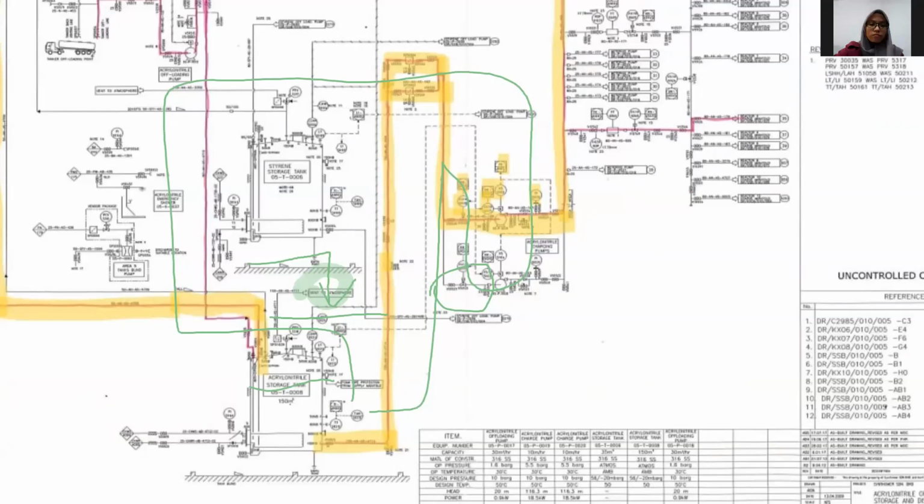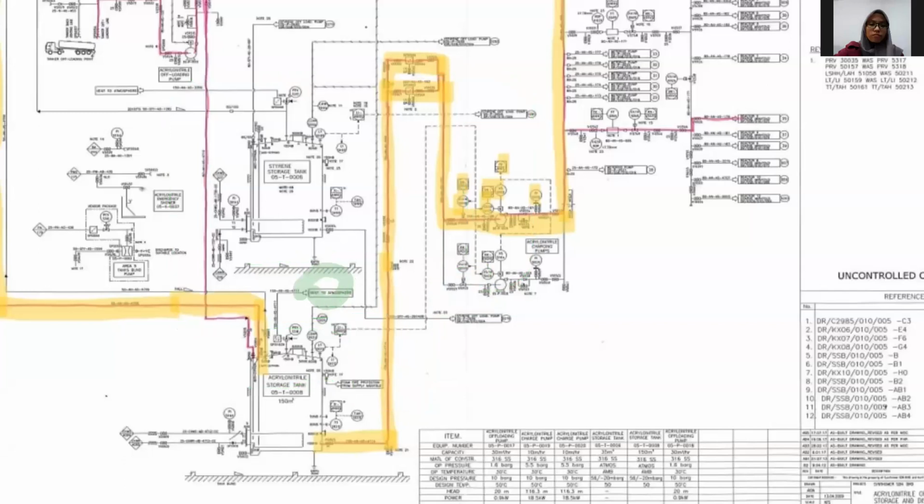The pump has to be primed to release the airlock, and then the tank will be filled with demin water and circulated for 1 hour. Connect the hose to nozzle A of this tank and supply the steam until it reaches a constant temperature, still at 70, for the next step, which is the acid treatment.